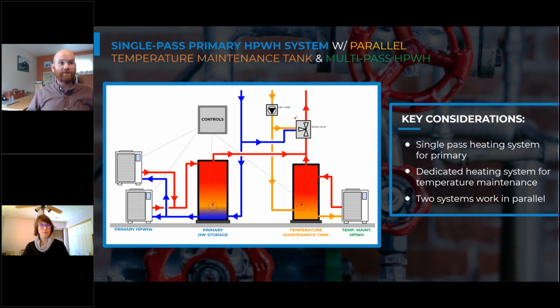So it's important to accurately size this mixing valve so that it can mix to those flow rates, because what we've seen is if this is oversized or undersized, however most designers are oversizing this, that it has good control over the discharge water temperature, the mixed outlet water temperature, when there's a high flow rate, so when there's a lot of use.